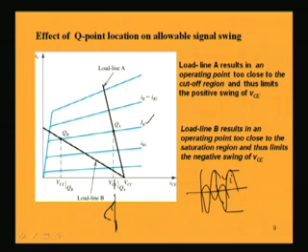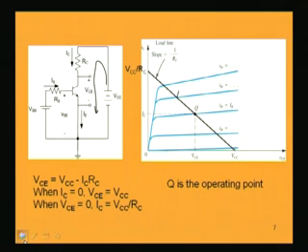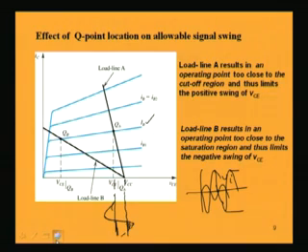So, if I see the VCE profile, now in the positive swing, I see that the instantaneous value of the collector to emitter voltage is clipped in this portion, because at any point the value of the VCE cannot be greater than VCC. VCC is the supply voltage we are providing. If we look back into the circuit, this is the supply voltage which is reverse biasing, which is VCC. So, at any point you cannot have a value VCE greater than VCC. So, our upper point, this point is fixed, we cannot go beyond this.